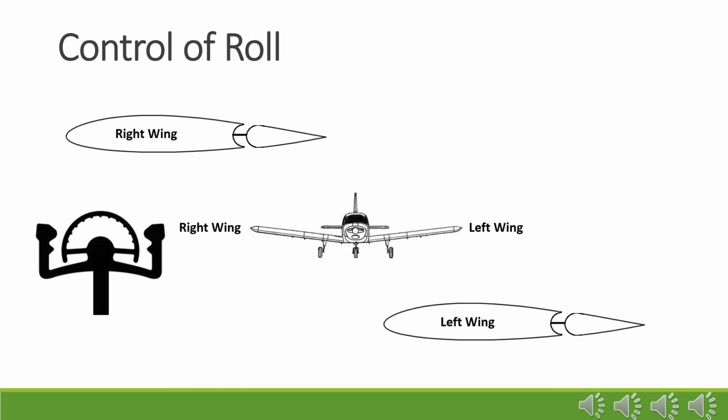Roll control using the yoke is very similar to that of the joystick. With a control yoke in the neutral position, the ailerons remain in the center position, there are no normal or perpendicular forces, and the drag force is minimized. The aircraft maintains a constant attitude.